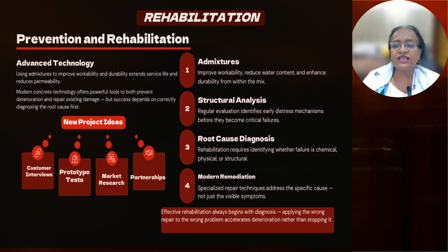People repair what they see instead of understanding why it happened. A crack is not the disease, it's a symptom. The real cause could be corrosion, foundation settlement, poor quality concrete, thermal movement, excessive loading, chemical attack, or even poor workmanship during construction. Unless that root cause is identified, every repair becomes temporary.